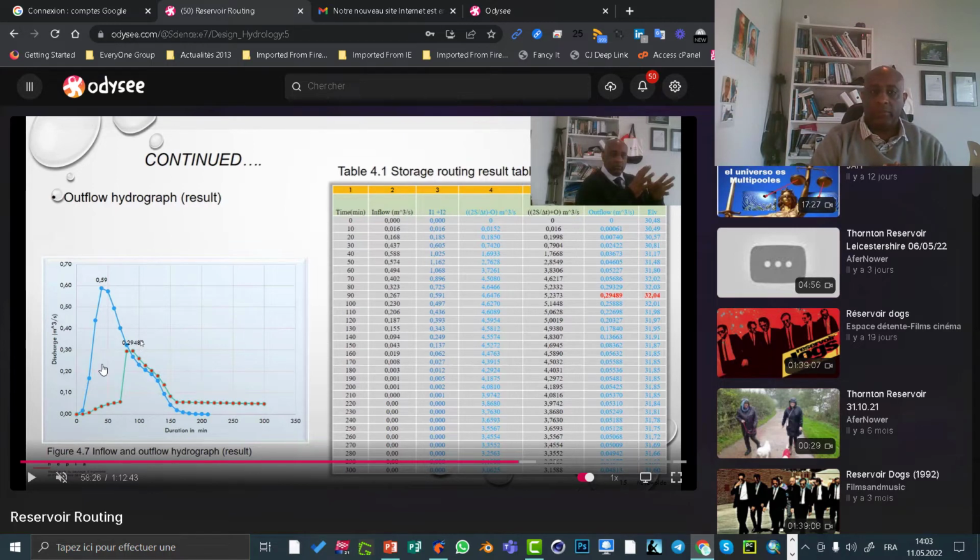That is how we calculate manually. You need to calculate, let's say, the area, something like that. But the HEC-HMS software calculates everything for us automatically, every detail. After calculating the hydrograph like this, it also tells us the storage, the water that is discharged, the remaining water, and the level of the pool at its maximum discharge. When the outflow is maximum, what is the pool level? That's also indicated. So it has some advantage, actually.